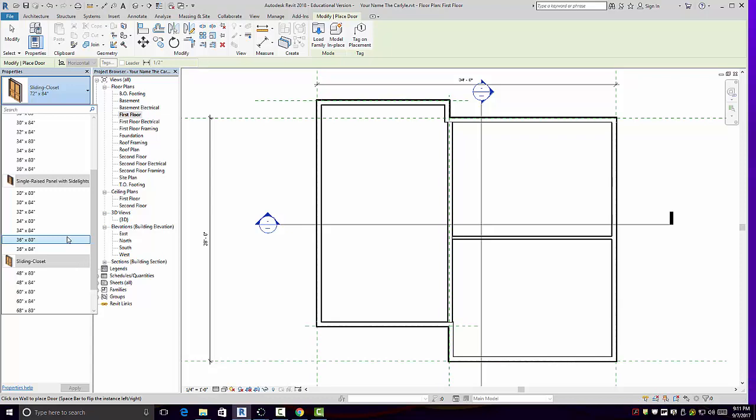You mean 7 feet, right? Right. Actually, you can get doors that size now. The old paradigm used to be doors were 3 feet wide, 6'8" residential. So you can use 6'8". That's the old style, but more modern houses are 7 foot, 7'4".